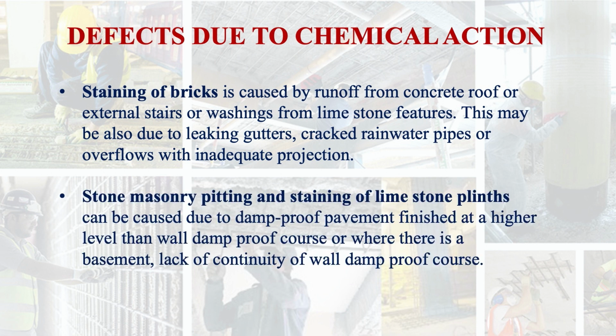Next is stone masonry pitting and staining of limestone plinths. This can be caused due to damp-proof pavement finished at a higher level than wall damp-proof cores, or where there is a basement, lack of continuity of wall damp-proof cores is there. So, in these situations this may happen.